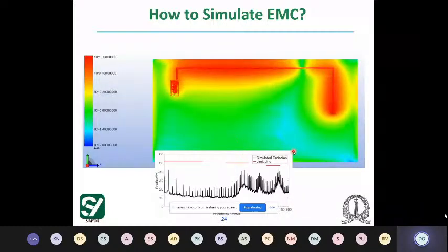If the current is known, then we do a current density plot on top of the system. This is the top view of the laboratory. Once the current density on the entire structure has been found, you can post-process and find every other quantity, like radiated emission, as shown here, also conducted emission, and so on. So this part of the problem is okay. And if the IC models are available, then I believe pre-prototype EMC simulation will be commonplace, and that's what we are looking into.